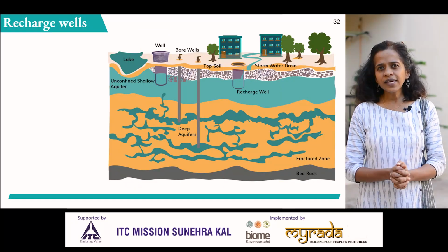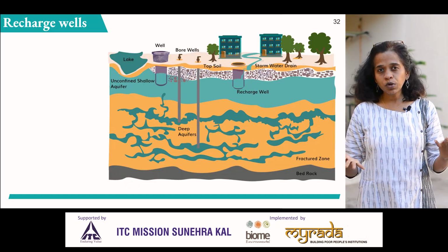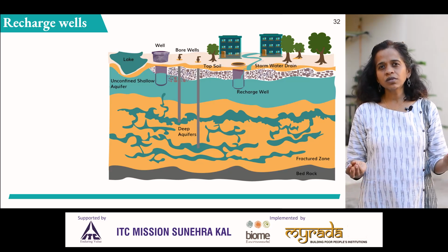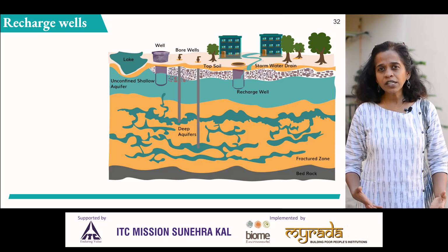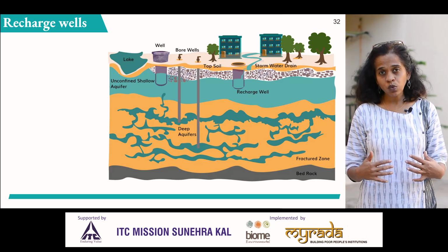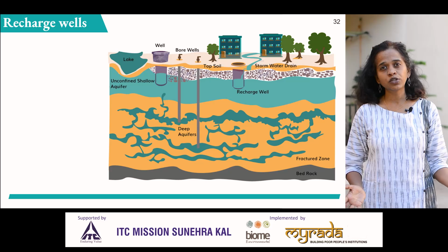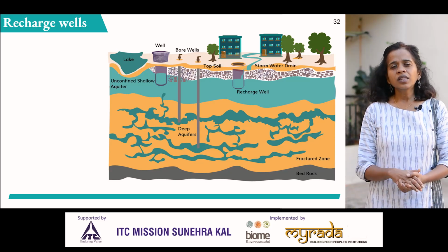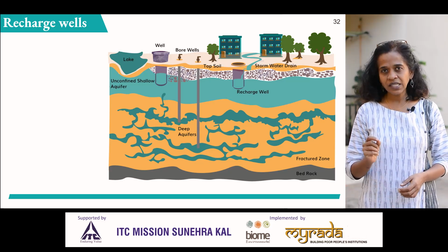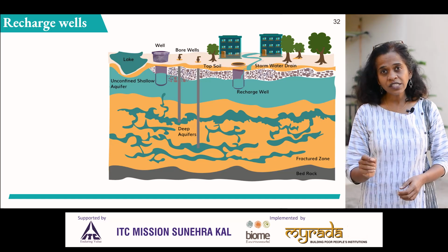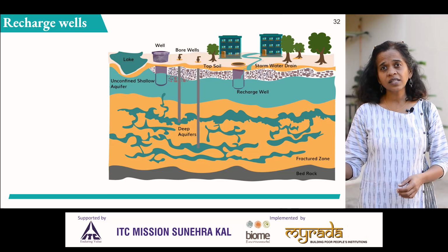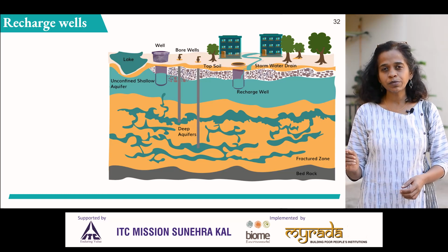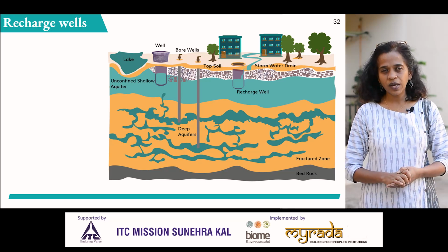The point to think about is when we are putting water into the ground, how do we put it, how much and where, and how do we make sure that maybe it's coming back to us or it's at least available to the city at large. The simplest and most cost-effective structure, and that can be built with regular local skills, not requiring any expensive machinery, is the recharge wells.